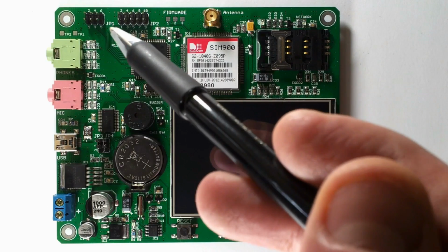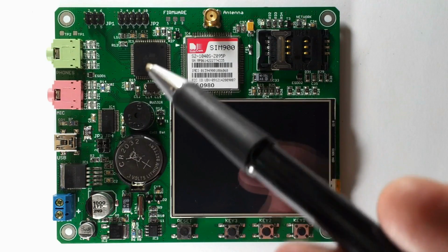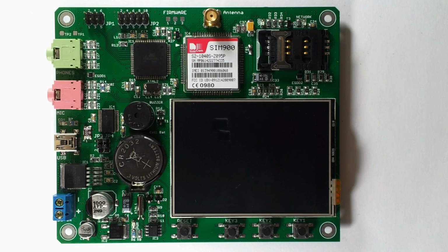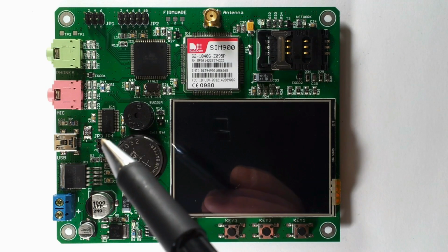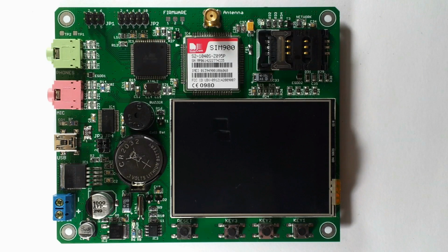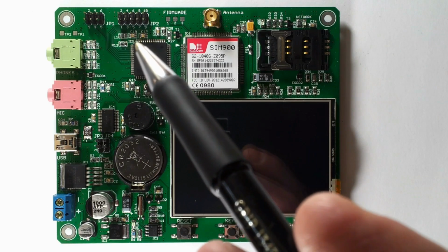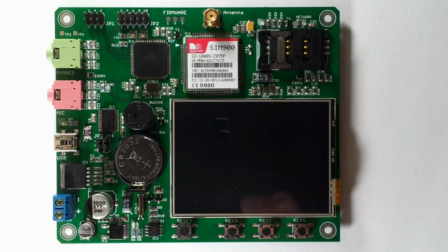Here's the ISP header for flashing the AVR. Here are the debug pins, if you remember that second UART of the SIM900 module. These jumpers here, I use them to select if I want to use the USB or I just want to access the I/O pins or flash the AVR, because these pins are shared on the Mega128, the port E1 and E0. On this 10-pin connector here, I have ground, VCC, and 8 I/O lines. I defined them as 4 inputs and 4 outputs, but you can do whatever you want with them if you write your own software.